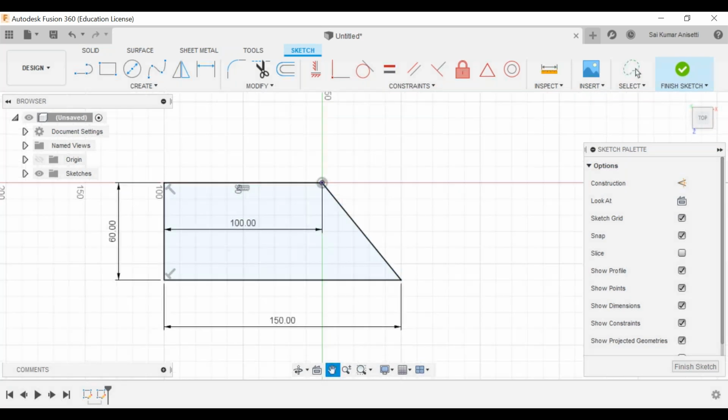And one more thing you have to observe in your sketch profile is color coding. See, if I hover my mouse onto the sketch, the selection is blue. Okay, and if I unselect it, it is black. The meaning of black is the sketch is fully constrained. That means you cannot move your sketch by simply dragging your line. Okay, that is one of your interview questions again.